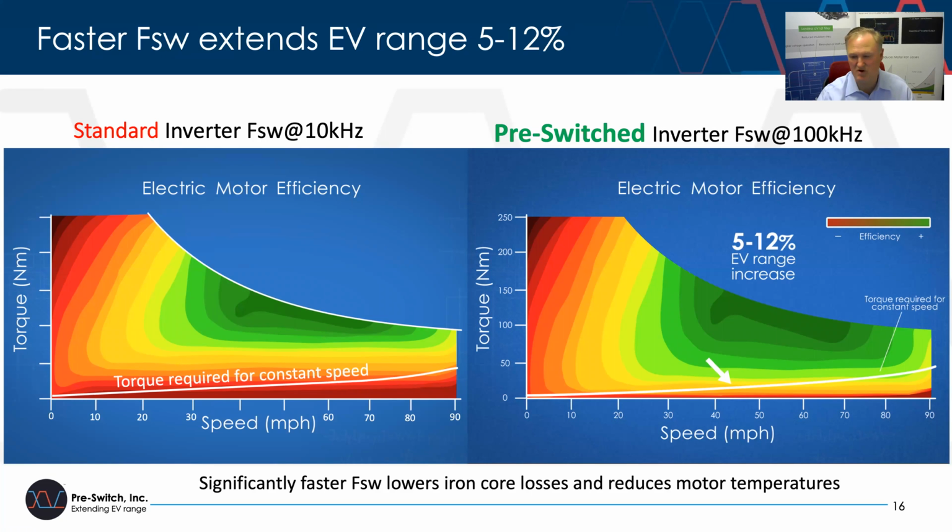We're actually working with multiple customers now that are designing our technology into inverters to prove this out. So the key point here is that the significantly faster switching frequencies can result in a much higher efficiency electric motor and increased EV range.